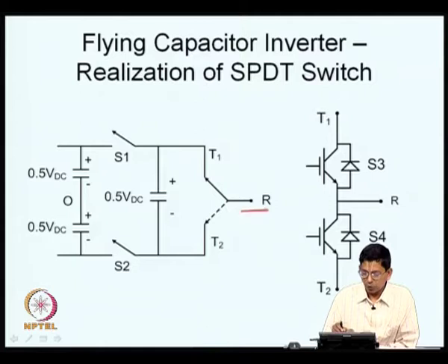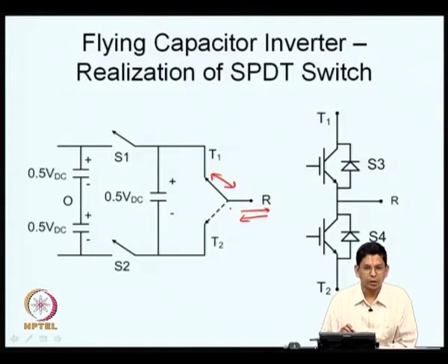So, as we said before, the current is bidirectional. Therefore, if the pole is connected to the top throw, the devices between the pole and top throw, or whatever switch comes between there, has to have a bidirectional current carrying capability. So, when that is there, this potential is now connected to the top throw and therefore, to the positive terminal of this capacitor. So, this comes here and this connects to the negative terminal of the capacitor.